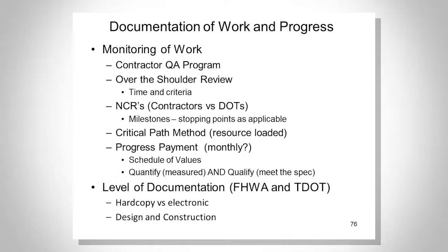Again, with NCRs, figure out if you want to have milestones to the point where, example I gave you, would you let the contractor pour on rebar that hasn't been blocked off the ground, or say unoiled or wetted forms? Again, those are decisions you need to make, because if something goes wrong and you need correction, it may be a little tough to get the contractor to see it from your viewpoint.